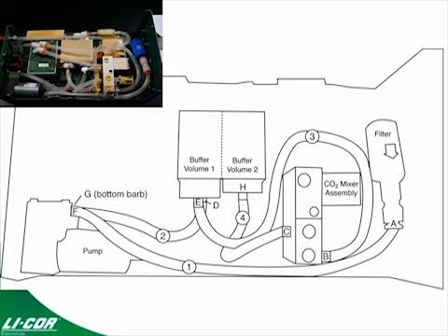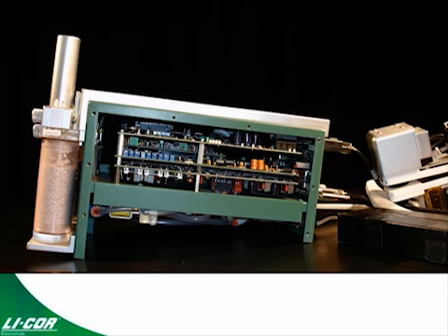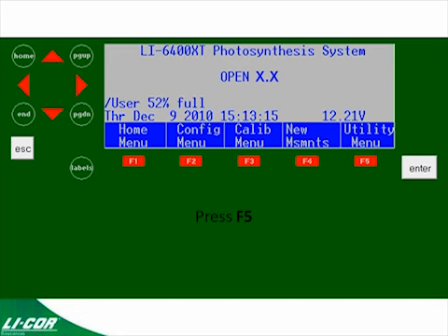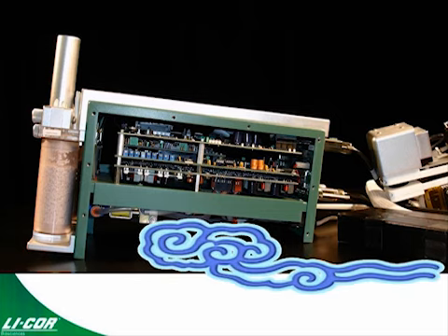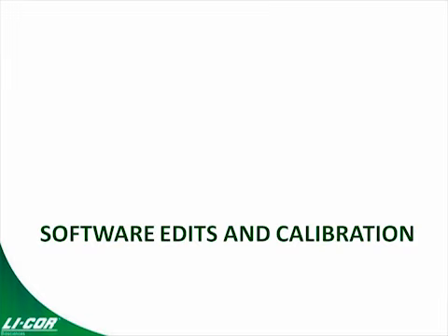Power the instrument on, being careful not to touch the internal components, and then with the system in new measurements, you want to gently blow underneath the carriage. This will allow you to see any spikes in CO2 concentration that may occur. You accomplish this most easily by setting the CO2 scrub to full scrub and the desiccant to full bypass. This will give you a zero concentration in both the analyzers, and so any increase will indicate a leak within the system.